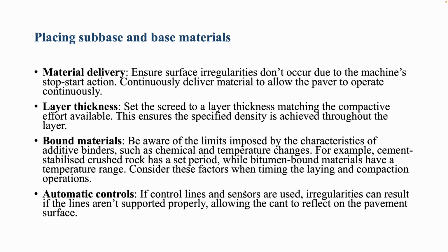this during placing. And for grade control, we'll use an autograde or self-propelled spreader, so that irregularities can be easily identified, preventing them from reflecting on the pavement surface.